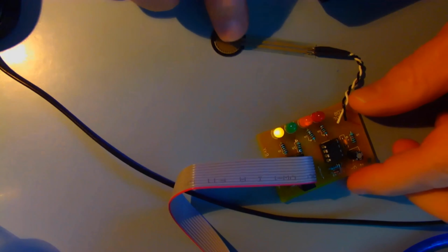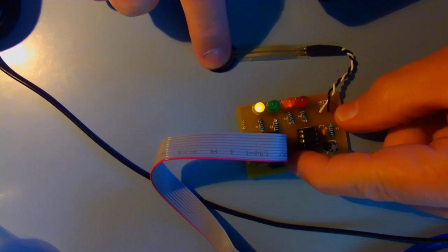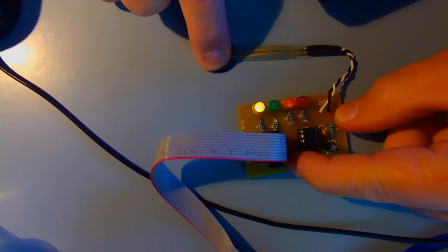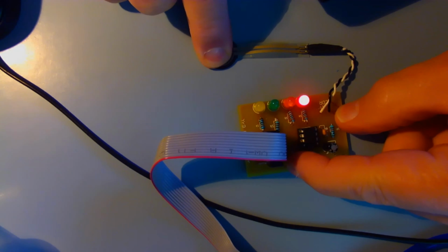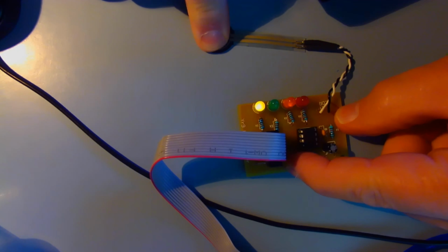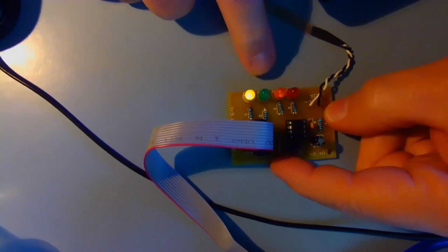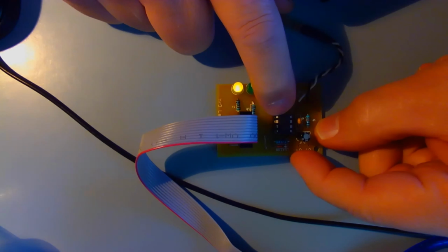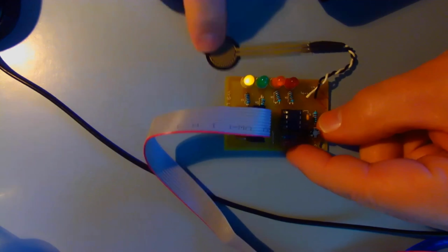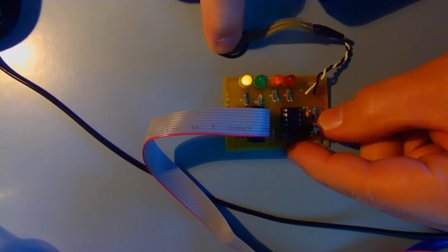There we go. So I've got this force sensitive resistor, and I'm going to put my finger on it, and put a bit of pressure on it. Okay, and as I press on it, you can see the LEDs change. So no pressure is yellow, a little bit of pressure is green, a bit more pressure is this orange, and then max pressure is this red LED. Okay, I've got to be pressing it really hard to get it to go on there. And you can see there's a very simple little board with this ATtiny85 on it. Cool little device. But I just want to show you this analog to digital conversion with the voltage divider, with an FSR and the voltage divider.